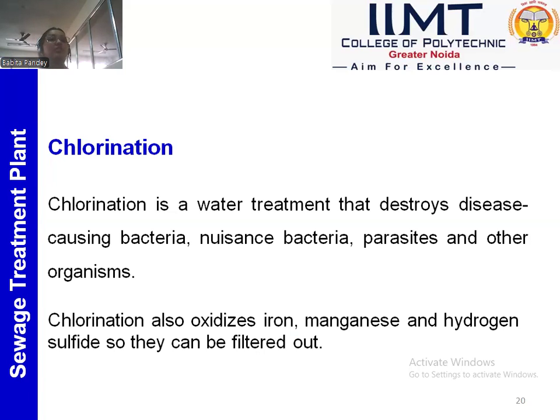So chlorination is a water treatment that destroys disease causing bacteria, nuisance bacteria, parasites, and other organisms. Chlorination also oxidizes iron, manganese, and hydrogen sulfide so that they can be filtered out.